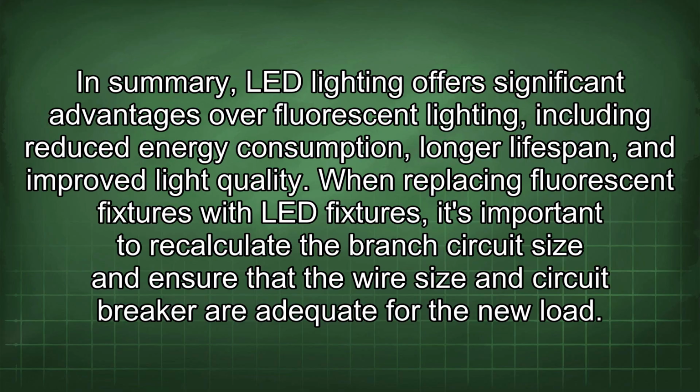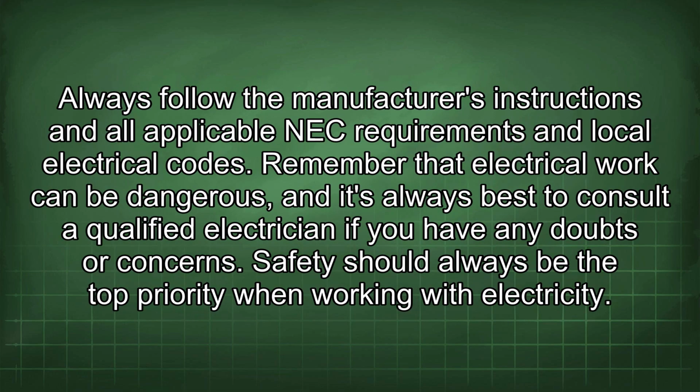When replacing fluorescent fixtures with LED fixtures, it's important to recalculate the branch circuit size and ensure that the wire size and circuit breaker are adequate for the new load. Always follow the manufacturer's instructions and all applicable NEC requirements and local electrical codes. Remember that electrical work can be dangerous, and it's always best to consult a qualified electrician if you have any doubts or concerns. Safety should always be the top priority when working with electricity.